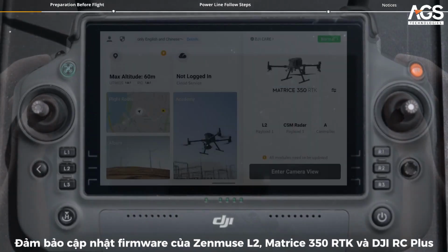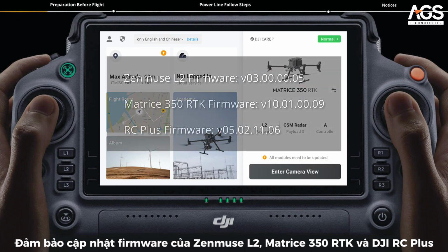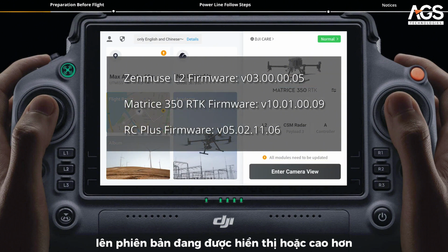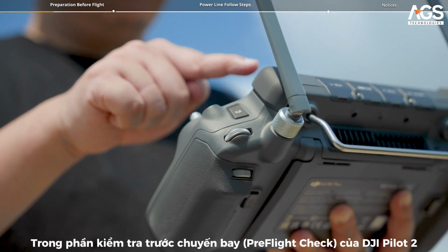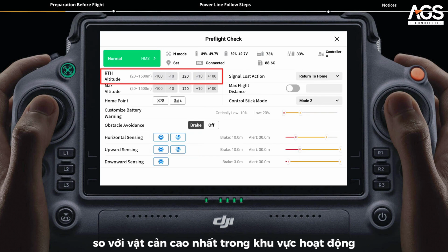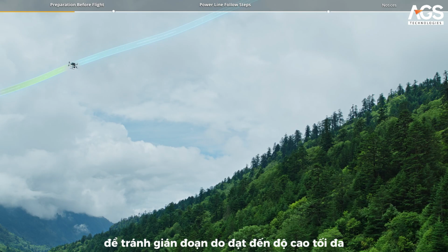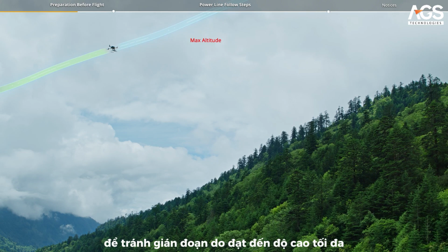Please update the firmware of Zenmuse L2, Matrice 350 RTK, and DJI RC Plus to the version displayed or above. In the pre-flight check of the DJI Pilot 2 app, set RTH altitude, and ensure the RTH altitude is at least 1 meter higher than the tallest obstacle in the operation area. Adjust max altitude based on the terrain of the flight route, to prevent interruption due to reaching the max altitude.